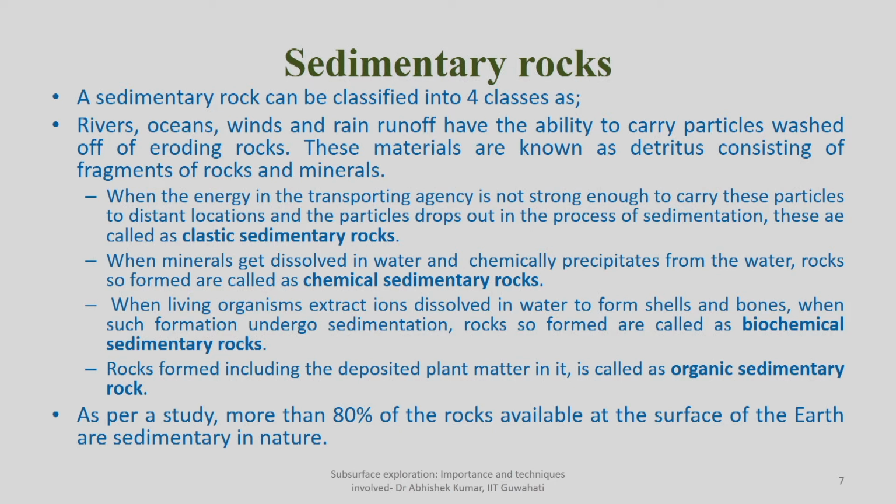Then you go for sedimentary rock, that is the second kind of rock. Depending upon the transporting agency and the chemical and deposition processes involved, a sedimentary rock can be further classified into 4 categories. But before going into this, we should know which agencies are responsible for weathering and erosion. Particularly river, ocean, wind and rain runoff have the ability to carry particles washed away or eroded from the rocks, the parent rock.